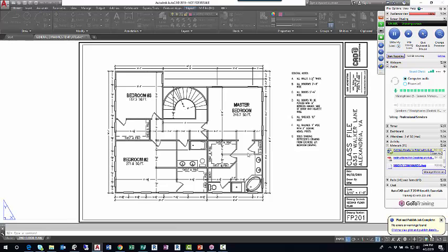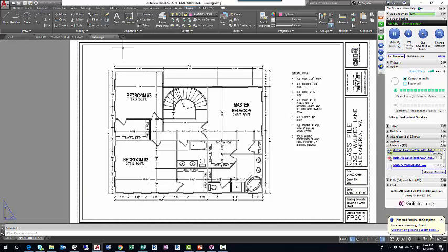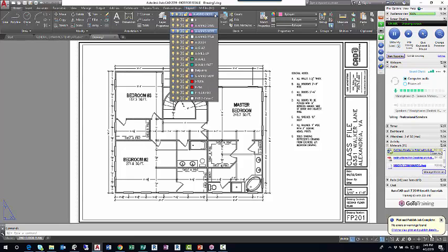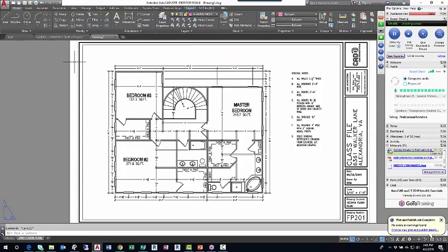Boom. I'll be in a drawing called Drawing 1 or Drawing 2, and again, imagine I deleted the floor plan. I could do a Save As, and this template will have the proper units, architectural units. It's going to have the right drawing limits for a building of my average size, in this case 50 feet square. The layers are already here. It's going to have a lot of blocks like window, door, all my plumbing fixtures, the text styles, the dimension styles, the print settings. So this would be a huge time saver, being able to start from a template like this as opposed to starting from scratch like we did last week sometime.